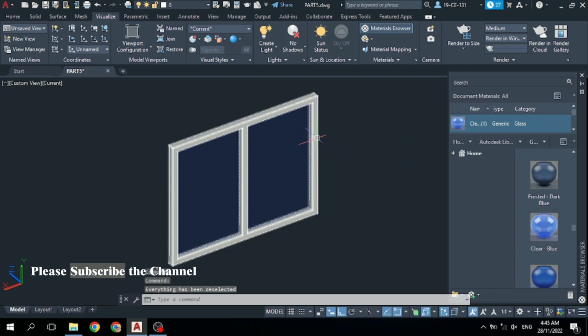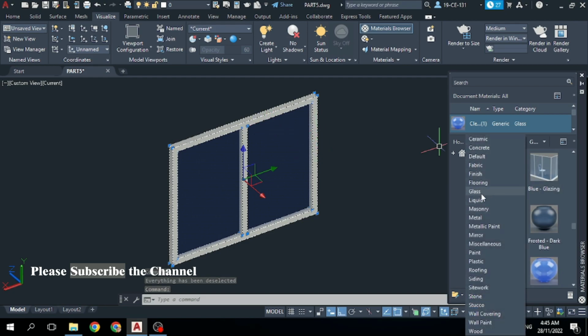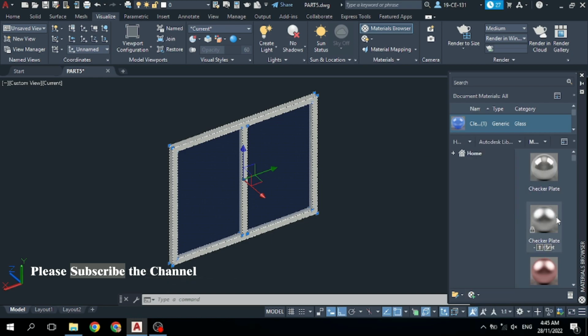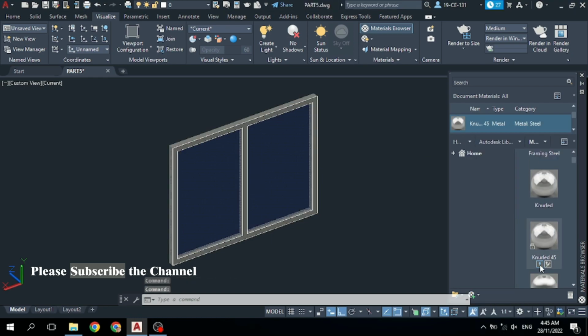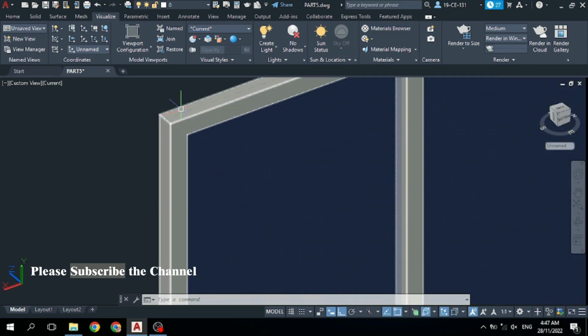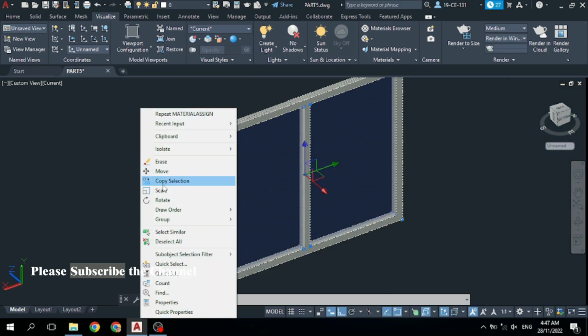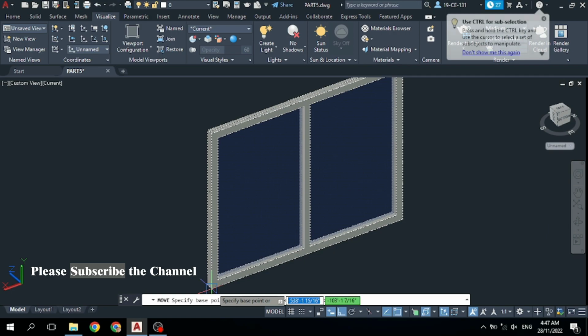And for this frame, you know that it is metal, so now I would like to add metallic material here. So simply select here metal and add that material. Let's click on it and select, you can select any of them. Now select this frame and this glass, and then right click and move it, specify base point.